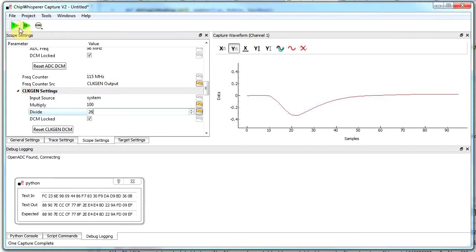and we'll see if they work. So now you can see the text out is matching the expected. So that's pretty interesting, because it's showing you that the core voltage is very important for meeting those timing guidelines. Now here it's failed, and again, this is almost undoubtedly because we're missing a lot of decoupling capacitors. So it's sometimes matching, but sometimes not.